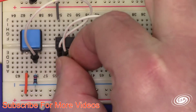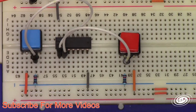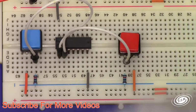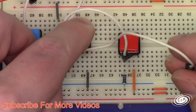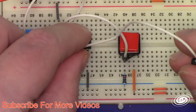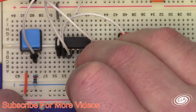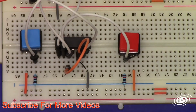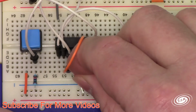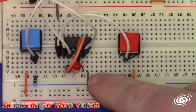So if I pull my LED out and turn my power off, let's take, for example, pin 3, which is my output. Take pin 3 and put that into pins 5 and 6 of my gate here. Then I'll come back and plug my LED into pin 4, which is the output of the second NAND gate.